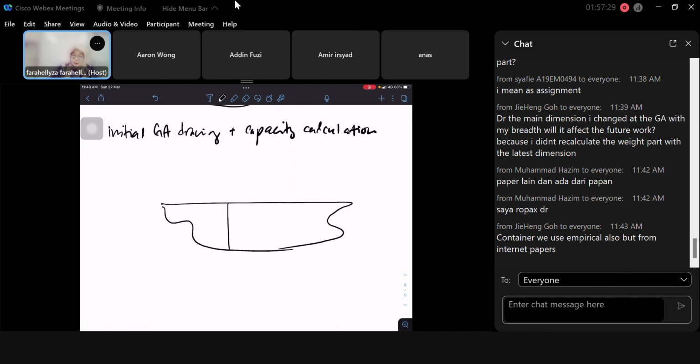So this is a bulkhead, and maybe you have several bulkheads, depending on what type of vessel. Maybe you have a double bottom here. Okay, so this is basically a cargo area. This is another bulkhead. This is your main engine room, ME room. This is your propulsion. Here maybe you will have a superstructure. I'm not sure, that also depends on the basic ship or reference ship. Maybe there are 3 layers or maybe 2 levels of superstructure.